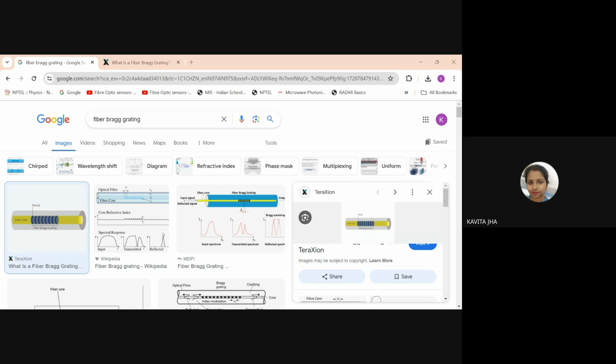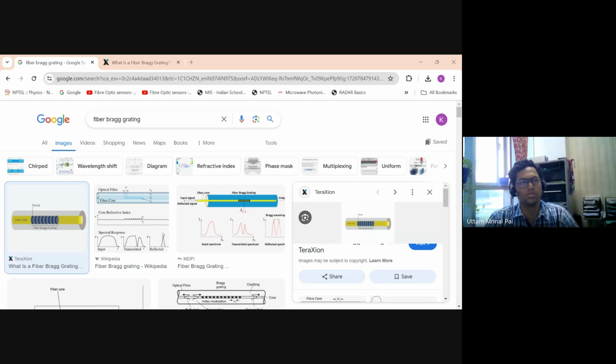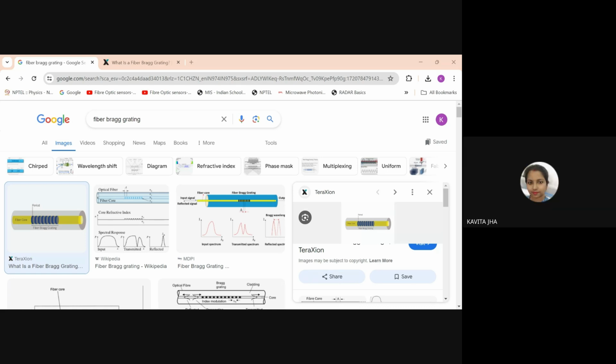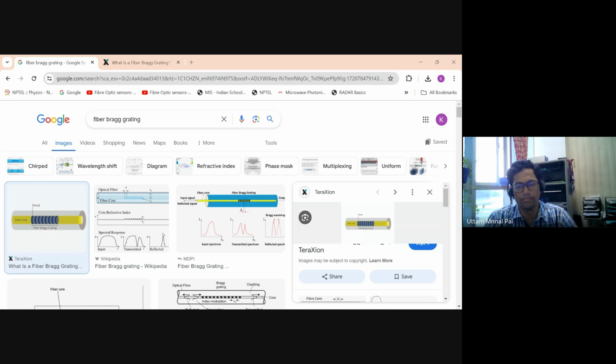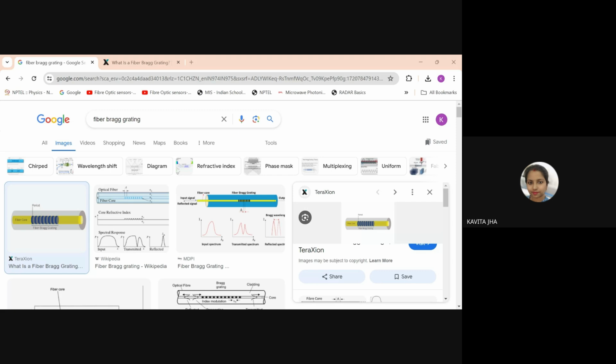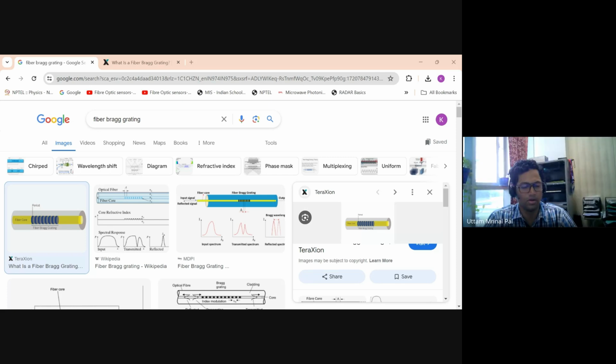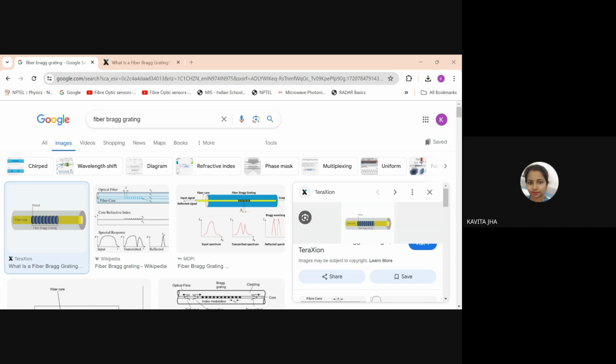And sir, what should I do first? Observing its transmittance and reflectance. As you're applying ports on both the sides, you can use S parameters, the absolute value of S11 squared. Sir, can you please explain how in the second case you chose S31 and S32, higher order? In this case there are no higher order diffractions, so you don't need to worry. You will get only S11, S21 and S22. The S parameter matrix would only be 2 by 2. Don't need to worry about it. Okay, sir. Thank you, sir.